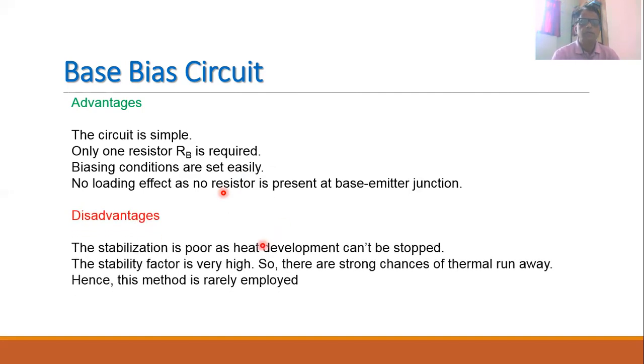But you will find that there are certain disadvantages as well. This circuit has poor stabilization. This is because when the circuit is operated over a long period of time, heat will get developed and the development of heat cannot be stopped in this circuit. This circuit has a stability factor which is very high. Now we require the stability factor to be low, but this is a circuit of which the stability factor is very high. Therefore, there are strong chances of thermal runaway.